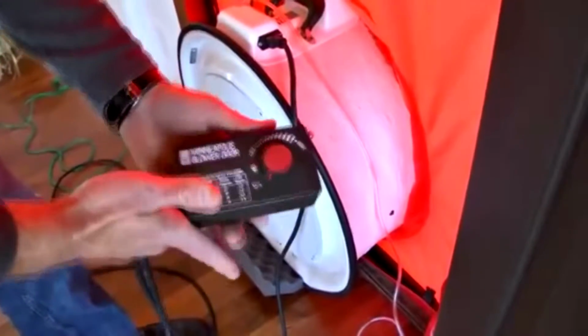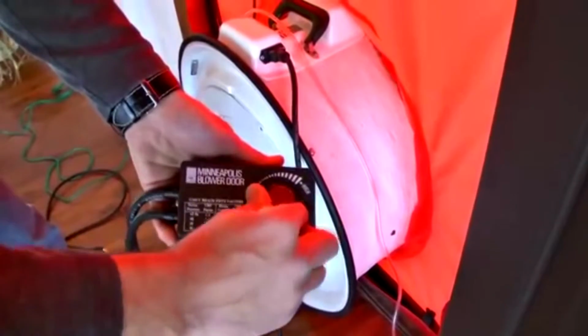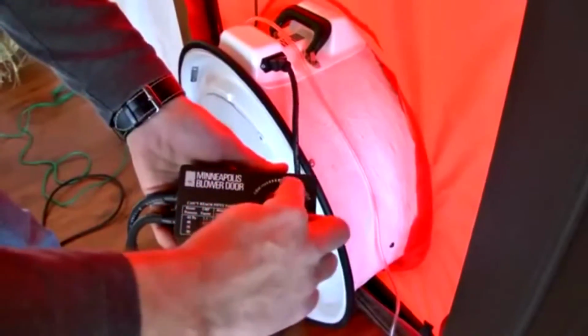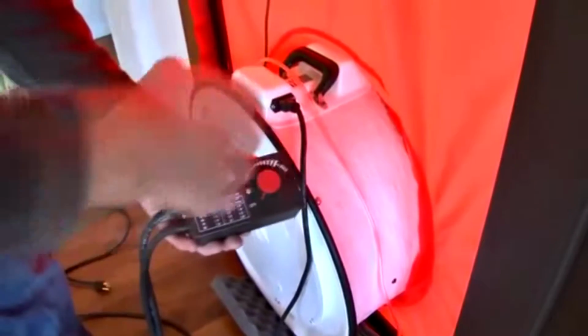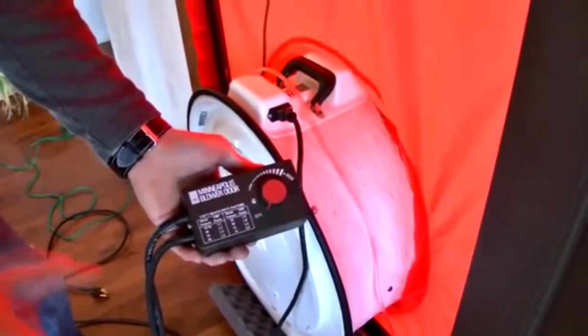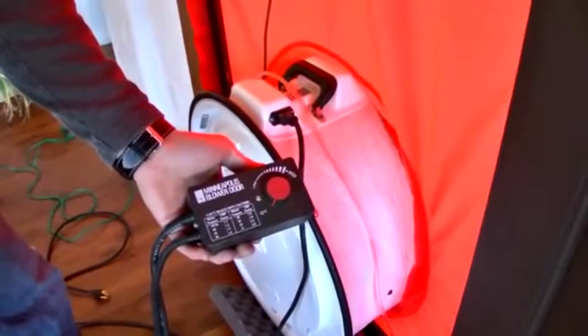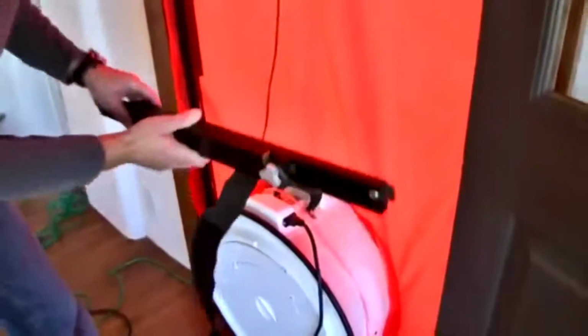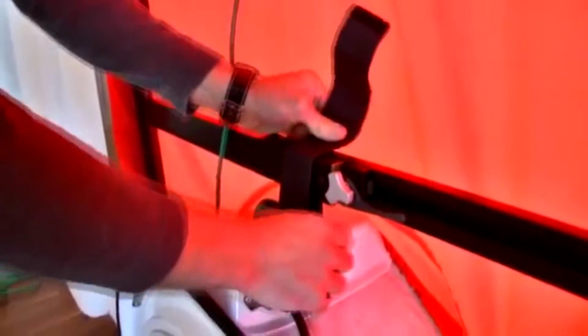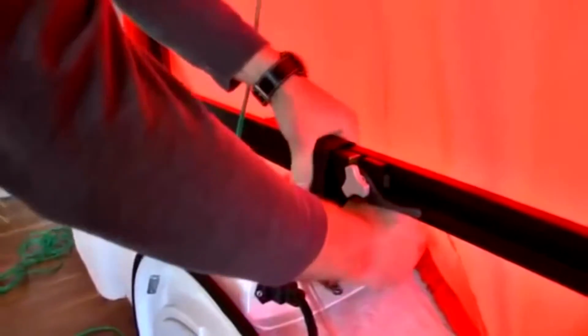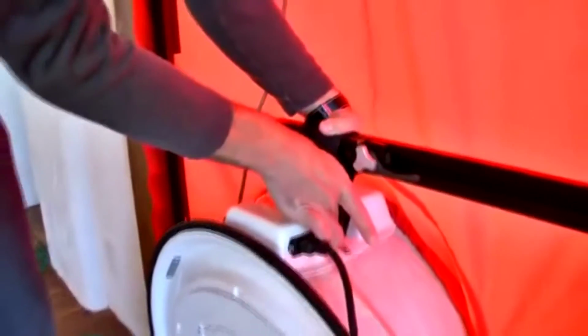So your rheostat here, this is just what controls the speed of the fan. And so you can see that you can just move that from low to high, and you're going to adjust how much flow is coming out of that fan to get your 50 pascals that we're looking for. I like to hang that on the crossbar here, so let's go ahead and put that in. And this crossbar is also here so you can really make that connection solid with the fan.